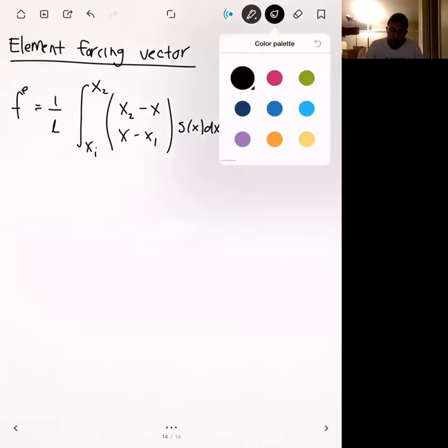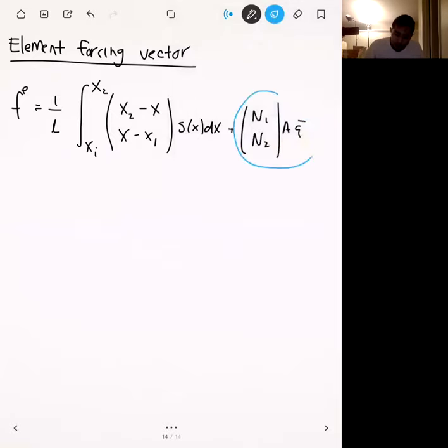And so first let's go ahead and evaluate this term on the right here. For element 1 or element A, we're nowhere near the Neumann boundary. So node 1 and node 2 of this element have no heat flux boundary conditions. And since there's no heat flux boundary condition for this, we can just cancel that term straight away.